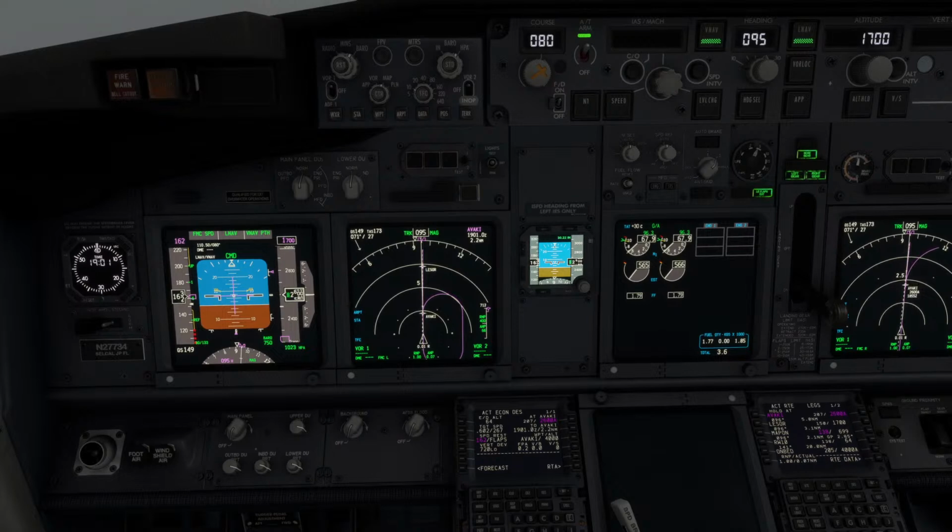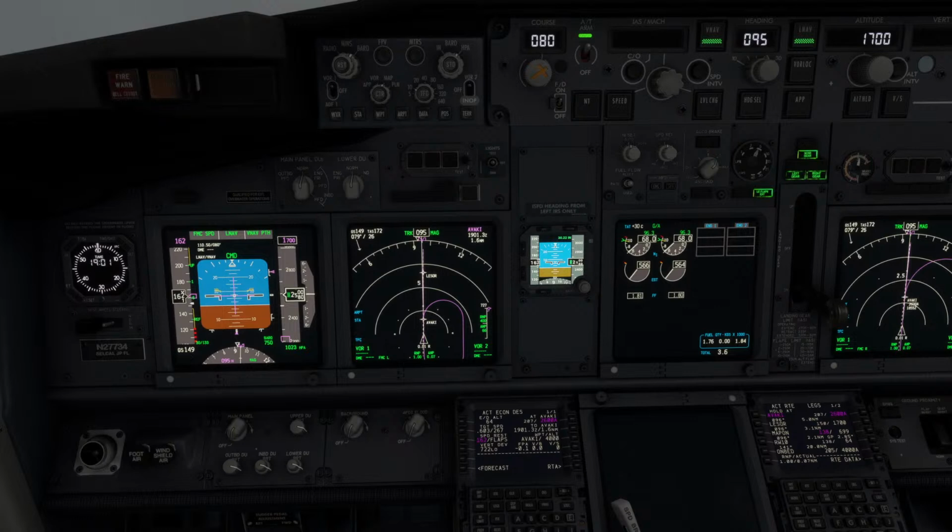So as soon as we start the descent on this approach, I'm going to select flaps 15. Remember, the landing gear is already down, it cannot be retracted. And then approaching Lessor, we are going to select flaps 30 for a, let's say, a normal landing with flaps 30. In case of missed approach, we call go around, we push TOGA, we make sure we have the thrust, we rotate to the pitch, and then we ask for flaps 15. We can retract flaps to 15 for this, but on the positive rate call there will be no gear up at this time. This is the main difference.